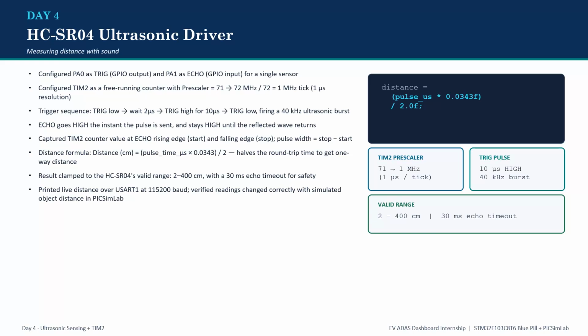The trigger sequence works like this: pull the trigger pin low, wait for 2 microseconds, then pull it high for exactly 10 microseconds, then pull it low again. That 10 microsecond pulse causes the sensor to emit a burst of ultrasonic sound at 40 kHz.